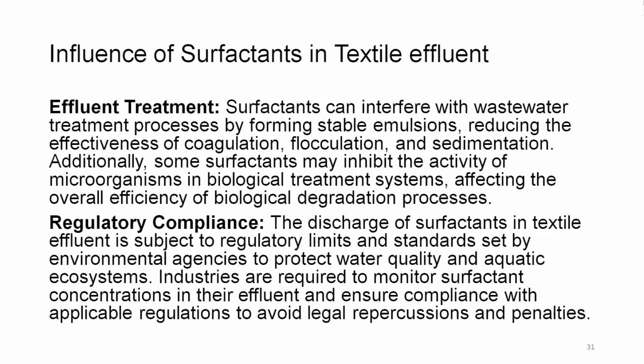Effluent treatment. Surfactants can interfere with wastewater treatment processes by forming stable emulsions, reducing the effectiveness of coagulation, flocculation and sedimentation. Additionally, some surfactants may inhibit the activity of microorganisms in biological treatment systems, affecting the overall efficiency of biological degradation processes. Regulatory compliance. The discharge of surfactants in textile effluent is subject to regulatory limits